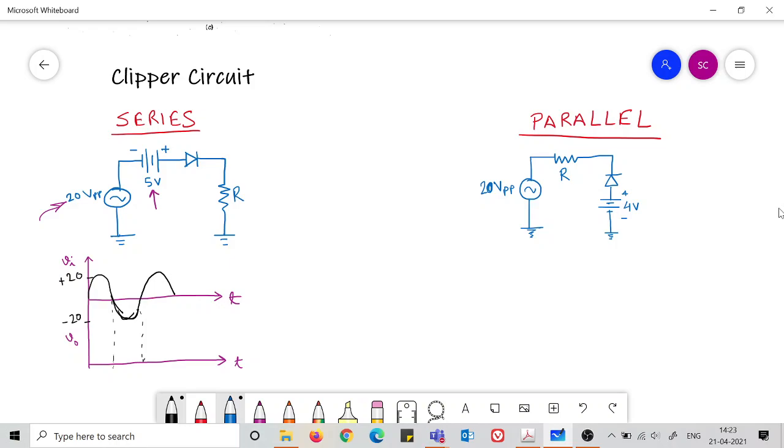So when this voltage is 0, what is the voltage faced by the diode? It is plus 5 volts. So it is on. It is in on condition. How long will it be on? You can understand this would be on as long as the voltage across the diode is not getting 0.